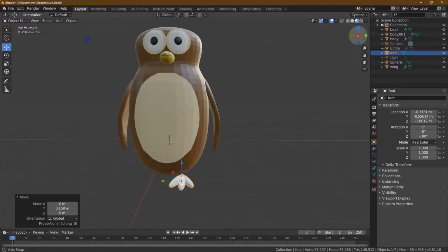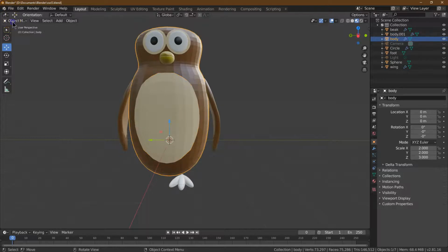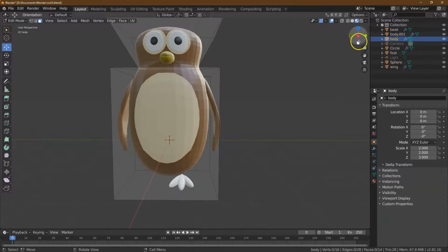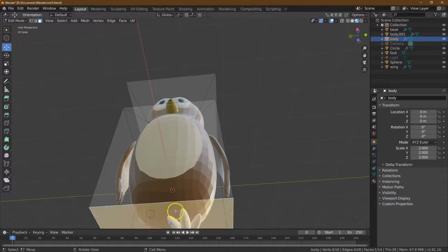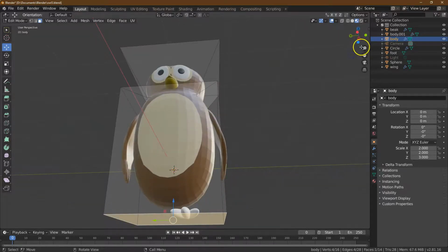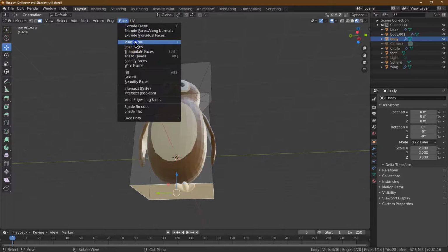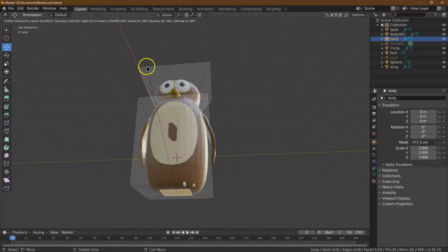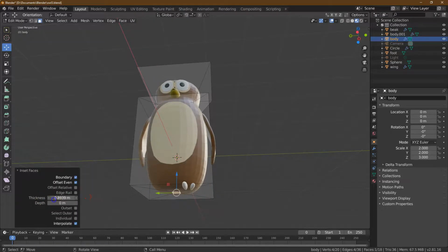And to make this fit a bit better so the bottom isn't completely rounded, I'm going to click on my owl. I'm going to go to edit mode. I'm going to click on the bottom face right here. And after I do that, I'm going to do a face inset. A lot. So my inset is 0.92. Okay, it just kind of hardens up this bottom so we can place stuff on it. Maybe even a 0.95. You would do a 0.99 if you want. All right, we just want it a bit flatter.